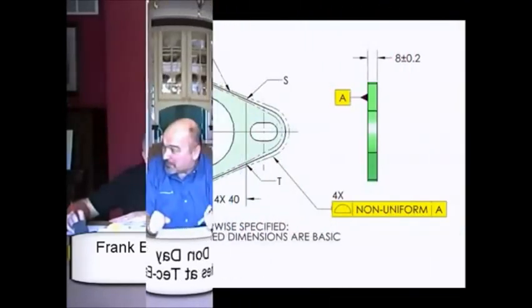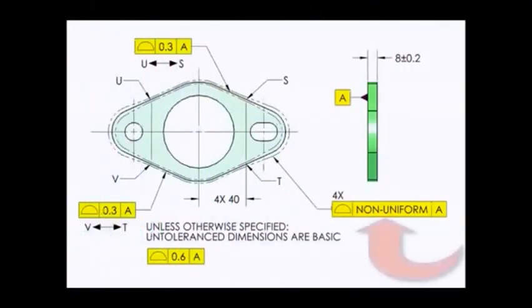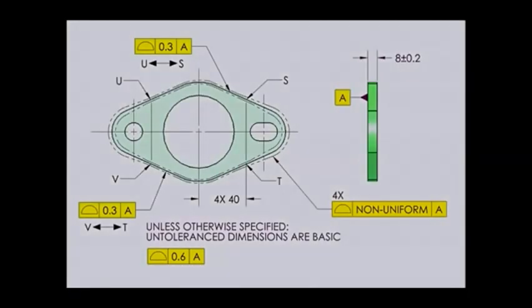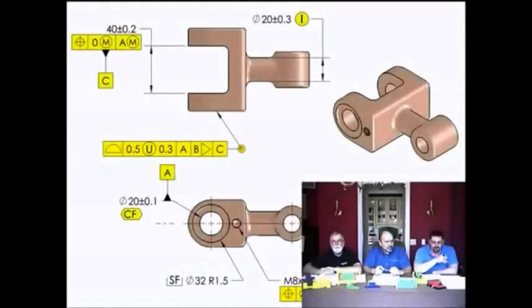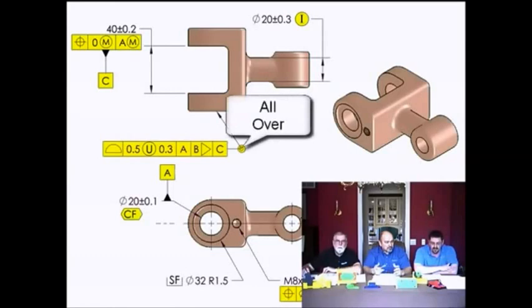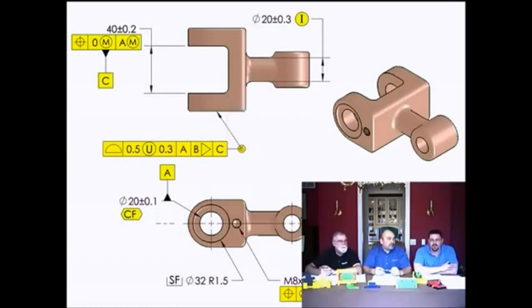Well, I guess looking back at it, the profile controls are kind of a big thing for me. They really expanded the surface profile section. The addition of non-uniform zones to smooth transitions between profile control zones is important. It's a new way of documenting it. They've included an all-over symbol where we used to have all around to control the profile around contiguous geometries. Now we have an all-over symbol. It supports general surface profile tolerancing, which has been a real big issue for moving towards solid-based design and manufacturing.